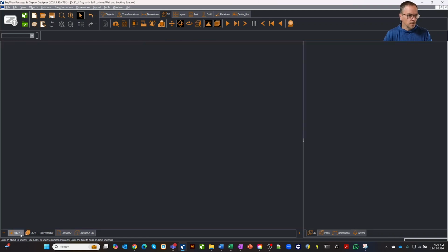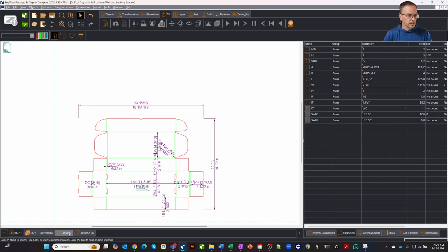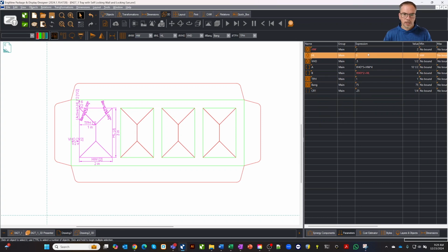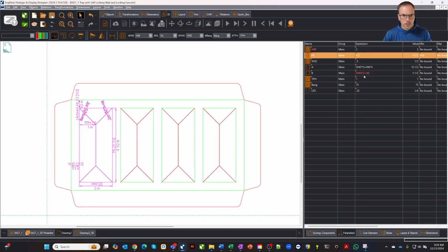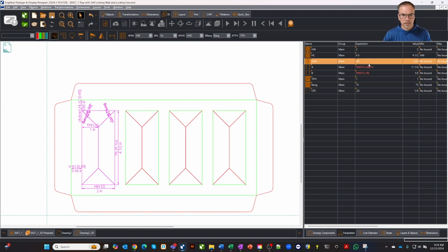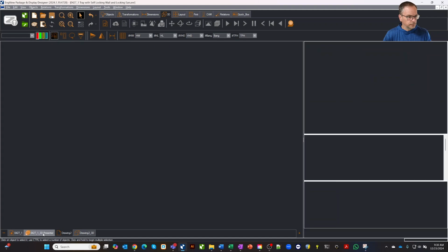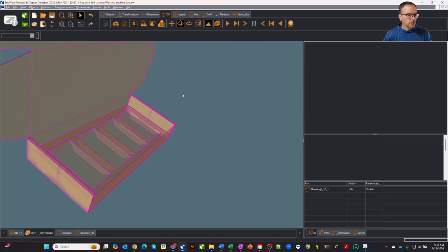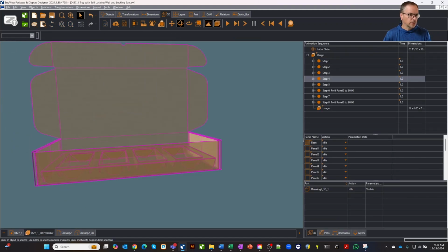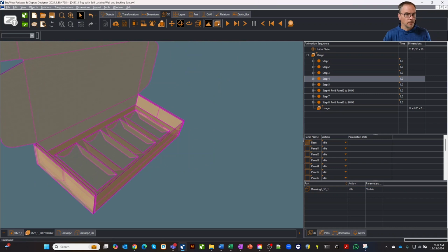Now let's resize our insert. Let's say that we want these lengths to be like 4.5 inches. We want maybe the vertical hole offset to be 0.65, so that spaces everything away a little bit. And maybe that tab height, we want to be 0.75, so that brings those sides down a little bit. Let's come back and refresh our design, and there you can see everything's adjusted. Your box is ready to make, and it's super quick if you look at that.